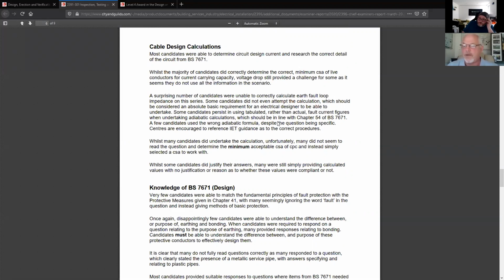Well, when you've got your conductor back in, you've got all your parallel paths. Your earth loop is going to be much lower. Your fault current's going to be much higher. Well, there's your difference. You can just say, oh, you need to have it disconnected, and then with the PEFC, you should have it connected. But in this exam, you actually just say, well, when you have it disconnected, you're removing parallel paths. And when you're having it reconnected, you're introducing those parallels, and you're reversing that, and you're therefore increasing prospective earth fault currents. And that's showing your understanding of the regulation's purpose.